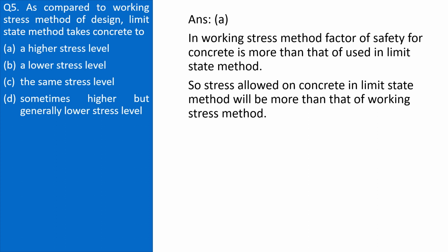Question 5. As compared to working stress method of design, limit state method takes concrete to option A, higher stress level, B, a lower stress level, C, the same stress level, D, sometimes higher but generally lower stress level. The answer is option A, the higher stress level.